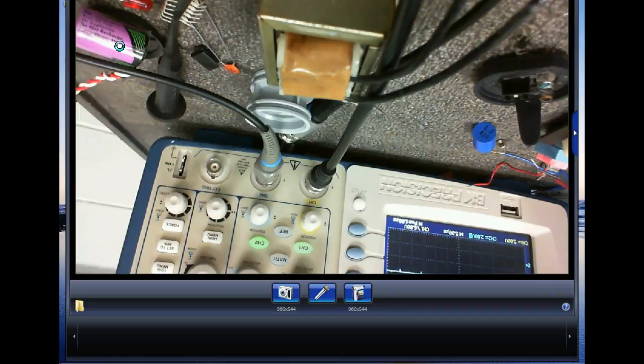In AC and also motor control, we talk about something called power factor. What happens in AC circuits is these devices cause a phase shift between the voltage and the current. In your power supply, these guys are notorious for having a very poor power factor. The more expensive ones with the power factor correction circuit in there are really filtered nicely.